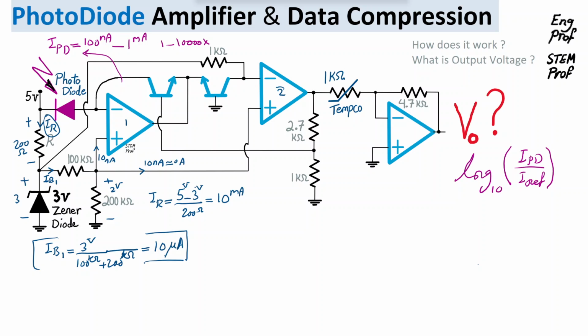So for op amp 2 and op amp 1, we have 2 volt sitting DC at the positive input terminal, or non-inverting input terminal. With the proper operation of the circuit, these op amps are in the linear region, so they have negative feedback. As a result, the negative feedback will enforce the virtual short for the op amp, which means the positive and negative terminals would have the same voltage, which is 2 volt. So that 2 volt will appear at the negative terminal as well because of the virtual short between the positive and negative terminal. I'm going to write it here, 2 volt and 2 volt.